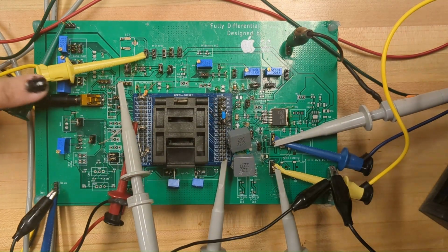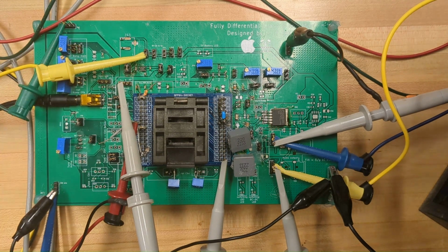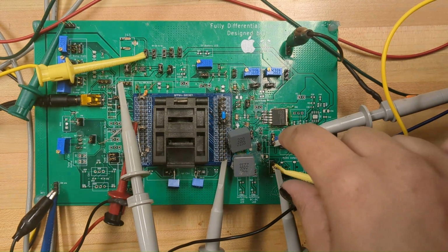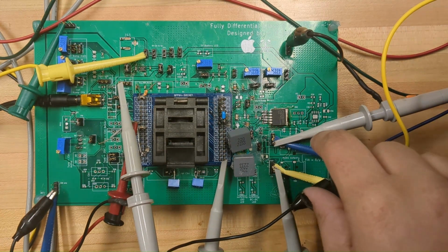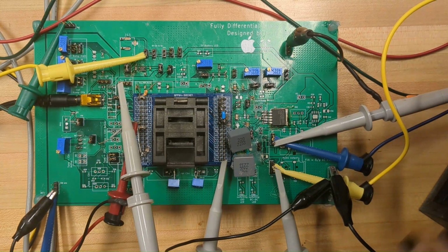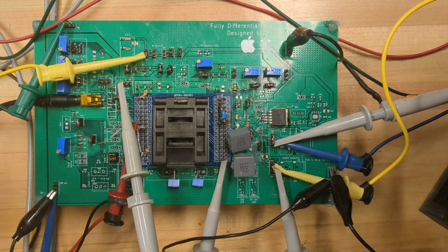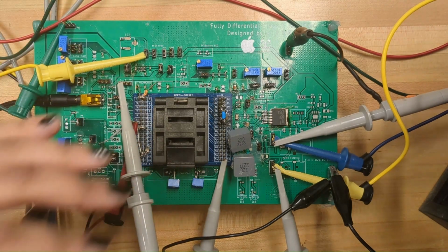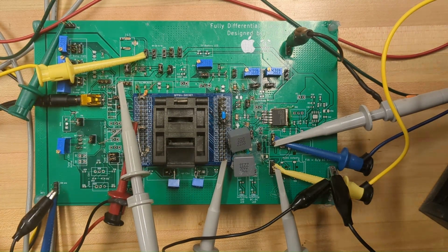This is where our input signal comes in, and we have an aux cable which feeds the input signal, and this is where our final outputs come from, and these are the signals which feed the speaker. We have taken care of routing our left and right channels differentially and in a symmetric manner on our chip as well as on our PCB to take advantage of rejecting the common mode noise which is present in our system anywhere.